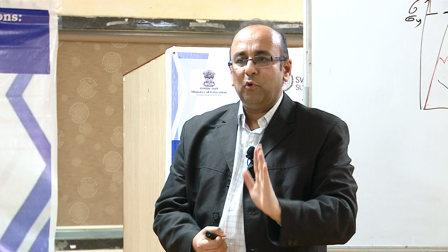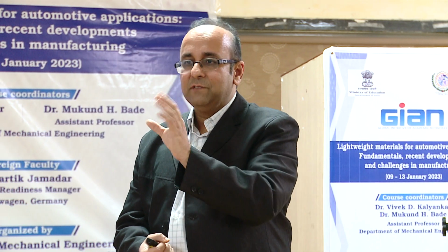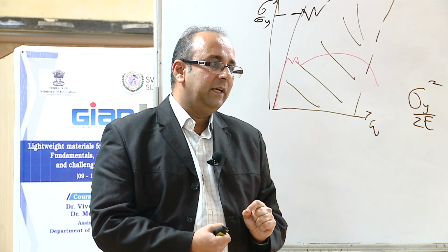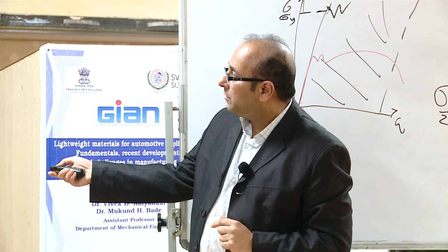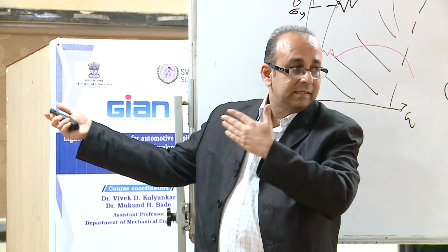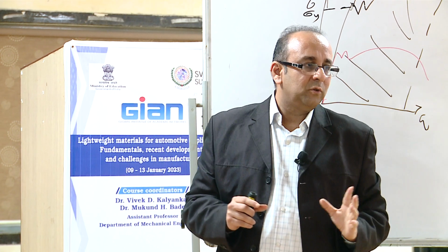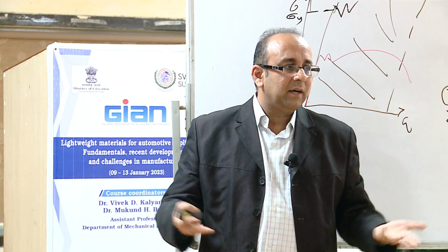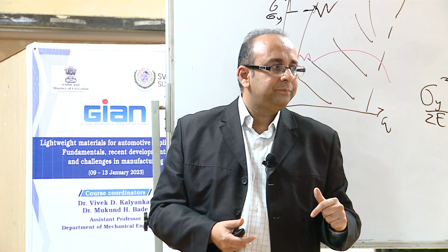So always when you go for high strength steel, the first question you should ask is, is it weldable or not? Because the problem occurs in welding. Now here I know that the best solution for my car is hot forming. So I have to find some solution also for the weldability, and that is the soft zone technology. We purposely make the area of the flange which is connected, suppose this is the roof area, softer by the soft zone technology. Otherwise that area will break, leakage will come, water will leak, and the part is basically not feasible. So without this soft zone technology, sometimes it is not possible to make the car.